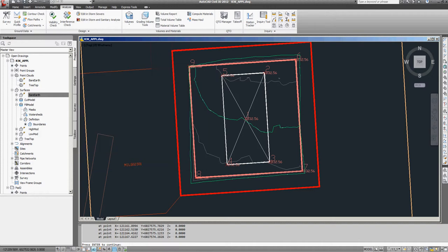However, some things we might be interested in are, for example, to widen out the area. If we did not want to have a 15-meter topsoil storage buffer, for example, we could move north, south, east, west this boundary so long as this green line here doesn't go outside of the red lease boundaries, because we are not allowed to do any earthworks outside of this boundary. So through an iterative process we can find the largest lease that can fit on a particular 130 by 130 square, and as well calculate what the net cut and fills are.